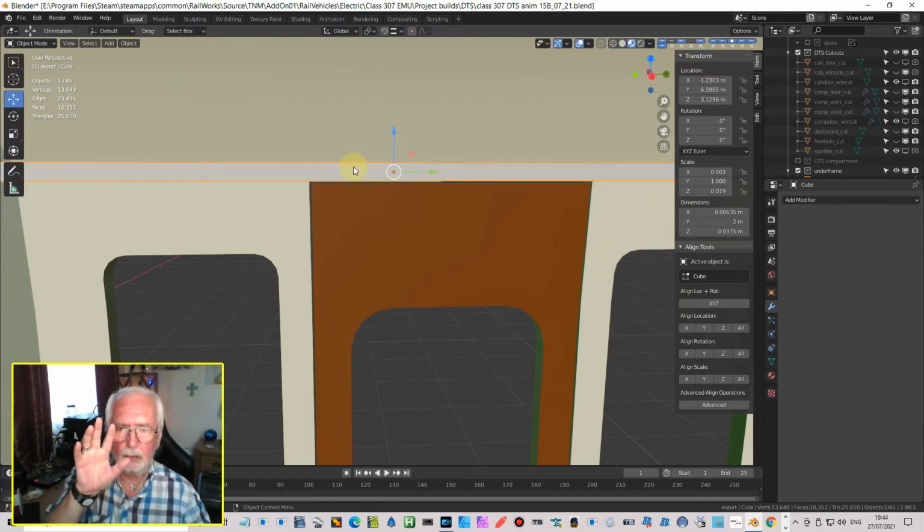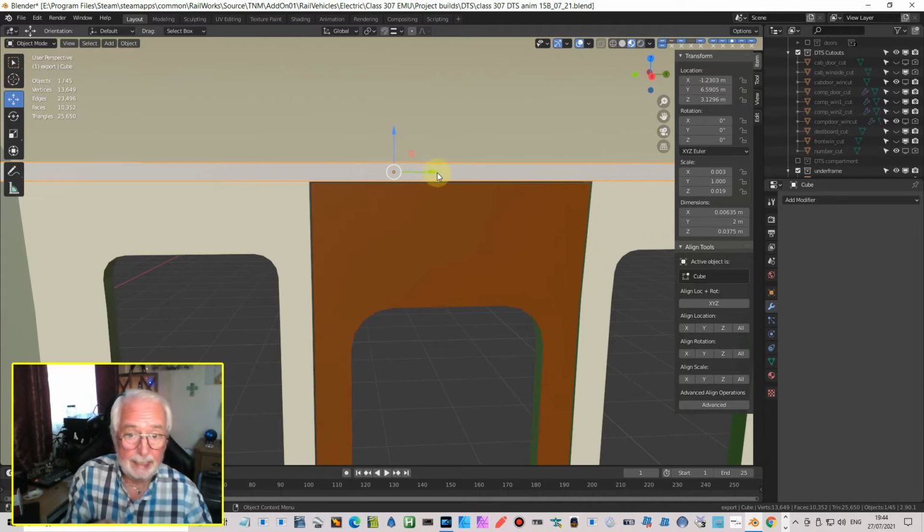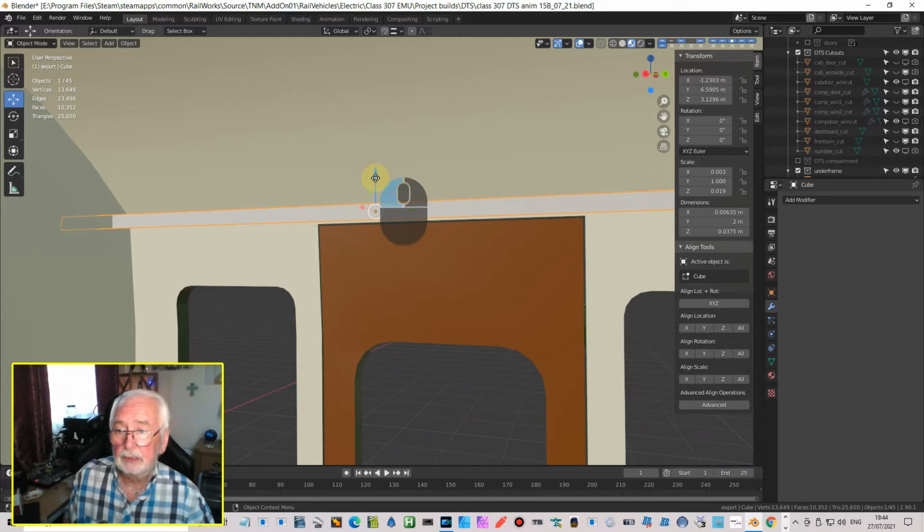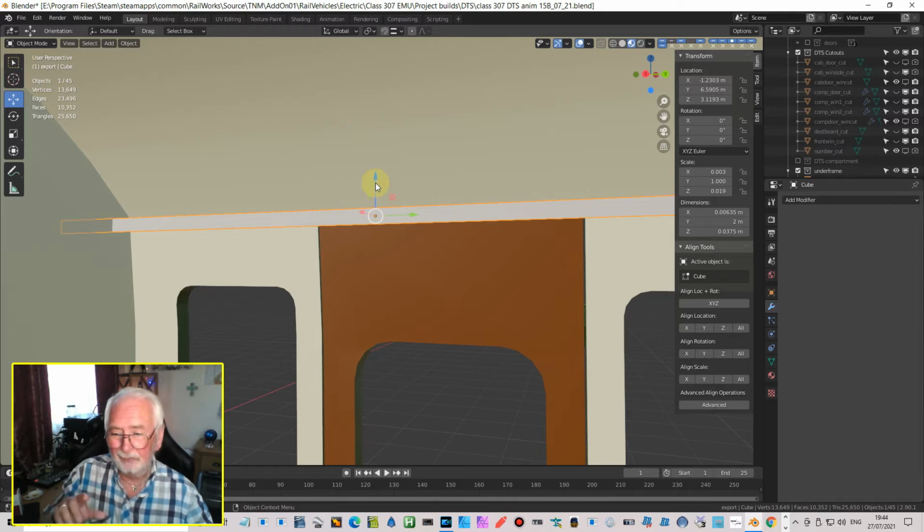So I think we've got 2-inch beading around the door, but also there's a bit of beading that goes the length of the carriage, or the width of the carriage, and I reckon that's about 1.5 inch and 3/4. It's almost the same size as the beading around the door, and that sits on top of this bit of beading here that is around the door. So even with lowering the doors, we're still going into the curvature of the roof there. So really, there's only one thing to do, and that is to literally raise the roof.